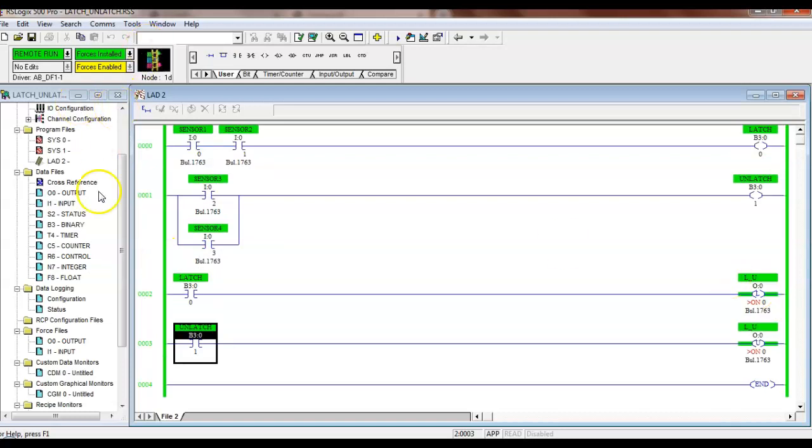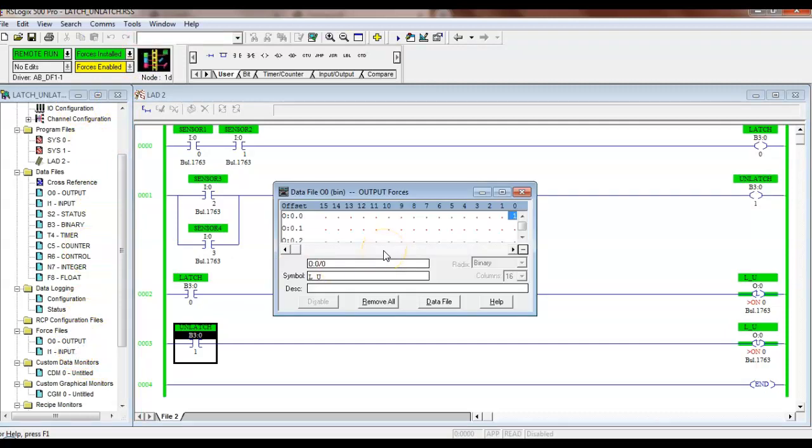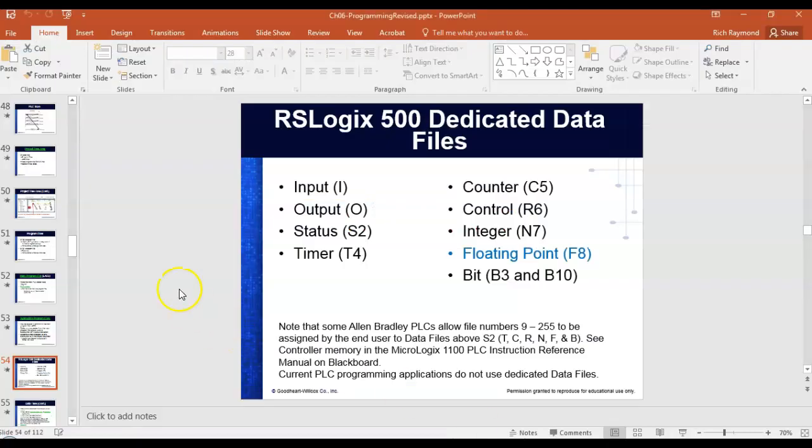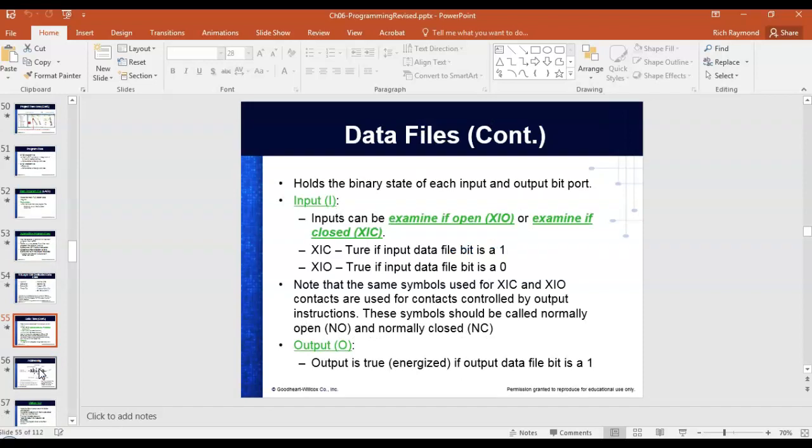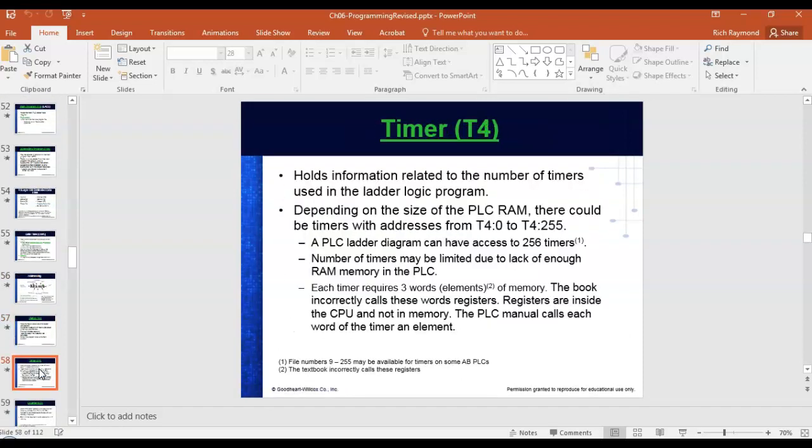I'm going to come over here and click on the output again. And then what I do to get rid of it, I double click on it, hit delete, and then hit enter, and it should turn off. It did turn off, but we latched it, right? So, what's the problem with using this? It's great for troubleshooting. So what would be the problem with doing this?